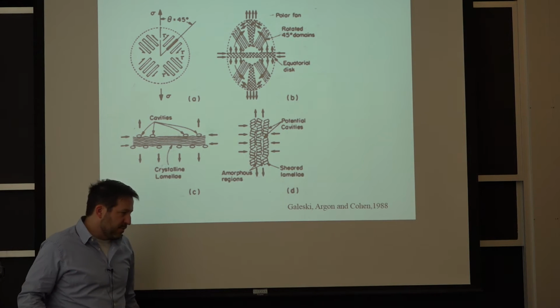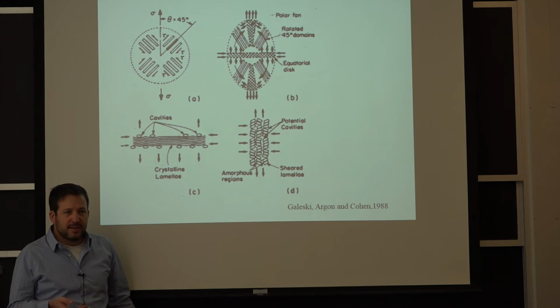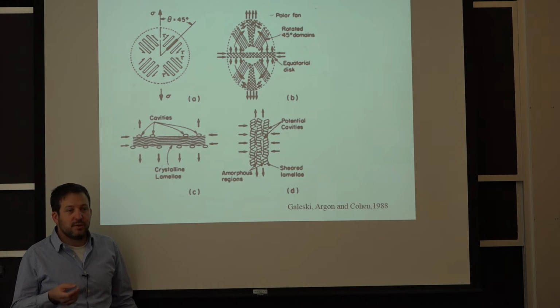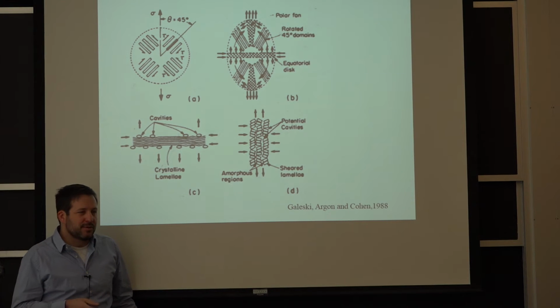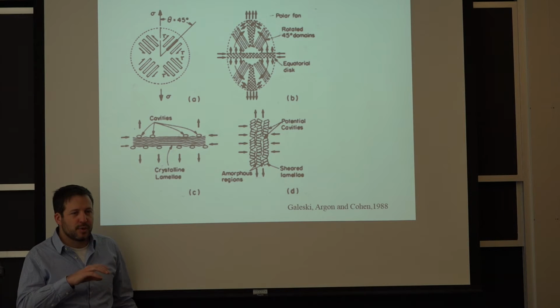And for some polymer, like polystyrene, that's the place they'll break, because now you've introduced enough tension that you have microvoid formation, and we'll go through that later. So if it wasn't for all this complex structure, you will not start forming voids very easily, but it's this critical stage as you start to transform that typically gets you to trouble.